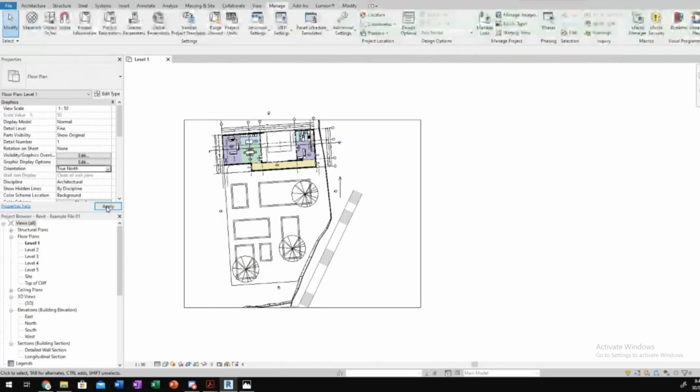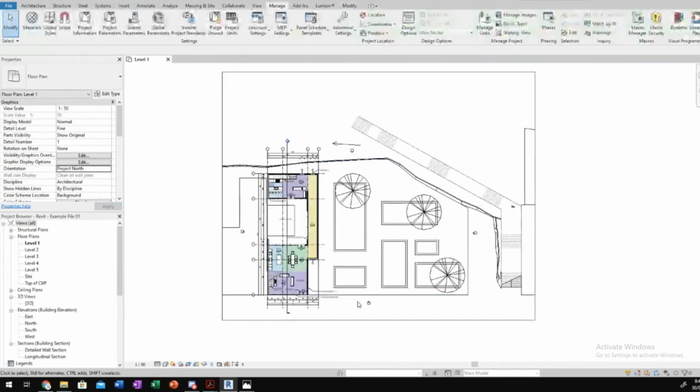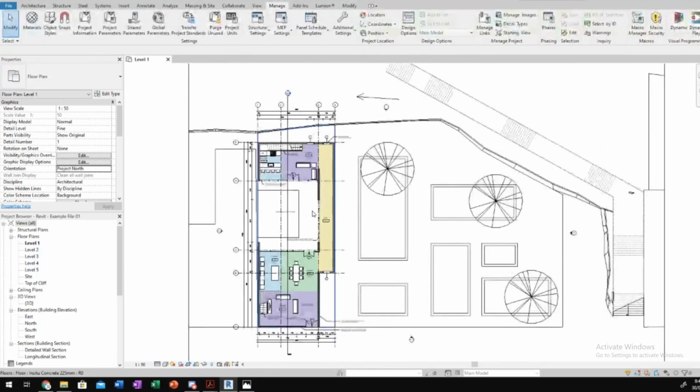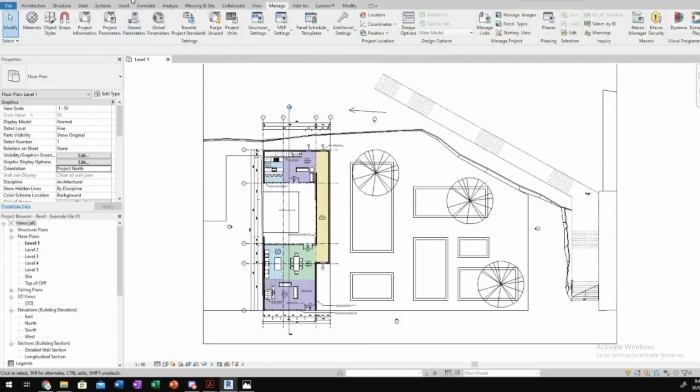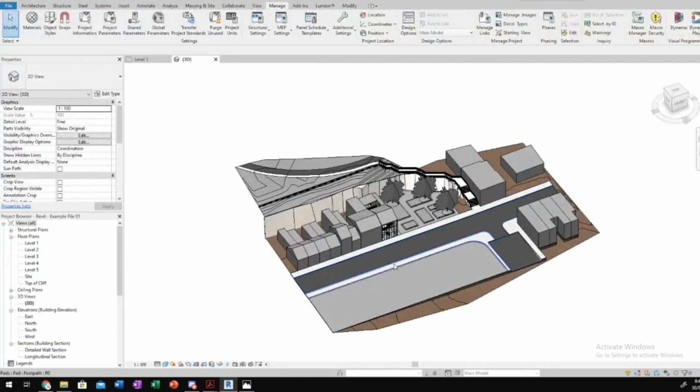Now that's one of the first things that you want to do when you set up a new Revit file. That's very important, and the reason why is for doing shadow studies. I love doing shadow studies in Revit because even if I'm building something in Rhino, I've made some masses, I'll bring them into Revit to do my shadow study because they do a great job at showing all of that. So up here is a great button that I love to use called 3D View.